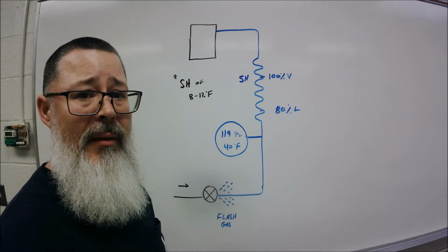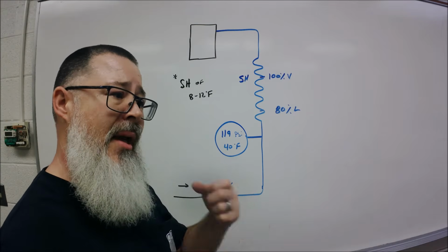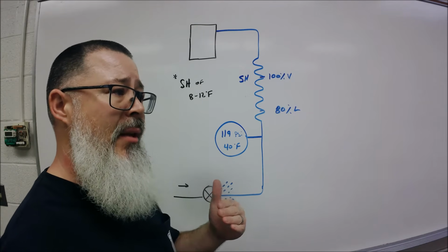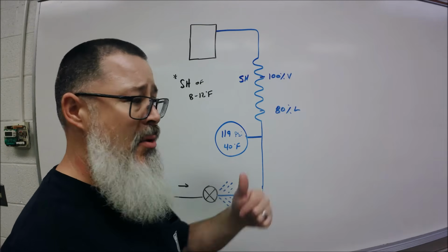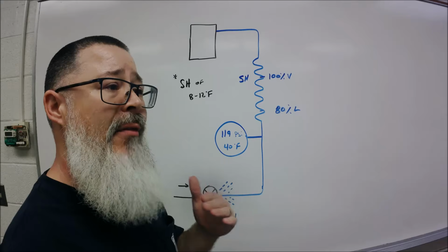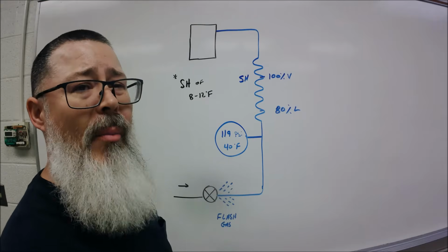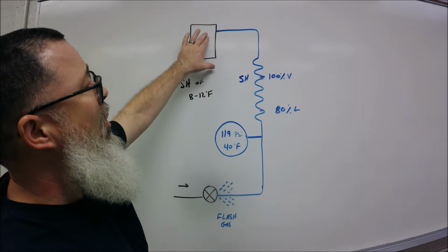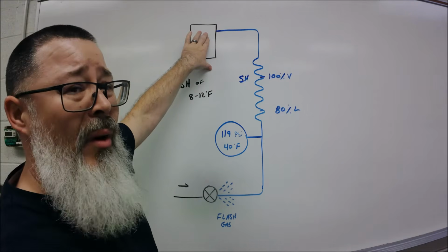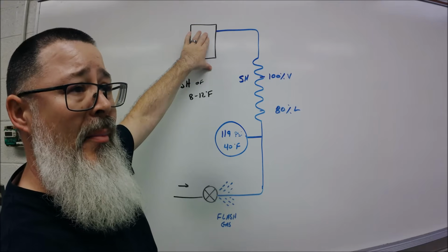But what does that mean? I tell a lot of my guys, you should be estimating what you should get, and then you need to verify and, of course, hook up your gauges, take temperatures, all your readings, and verify what the system is. But how do you go about thinking about it, all right? So this is me, all right? I like to start at the end of the circuit where I know the superheat's gonna be ending, right?